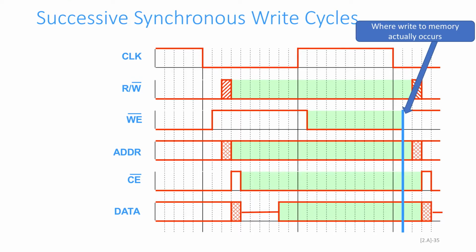When we're looking at when the write actually occurs to the memory system, again, remember that the SRAM doesn't look at the clock as an input. So the write is occurring when the write enable bit is flipped to high. Remember that these SRAMs are just simple devices, and when the write enable bit is flipped low, we're effectively telling the memory to read in the values on the data bus and just keep on reading these things in. It's like opening up the floodgates so that the memory can read in the values on the data bus. And then as soon as we turn that bit high, effectively turning write enable off, we're saying, all right, whatever value you've read by this time, we want you to latch that into the memory array, and then we're done.